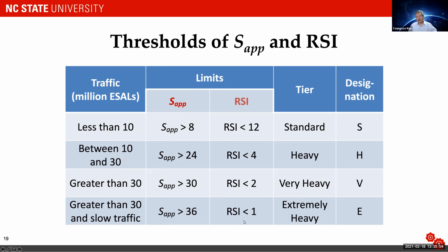So if you have a mixture for your region, by the way, these over 100 different mixtures are coming from all over the United States and Canada, and some from Asian countries and whatnot. So it covers a wide range of conditions. However, if you have a locally specific traffic condition and climatic condition, you may be able to test your mixtures and refine these threshold values.